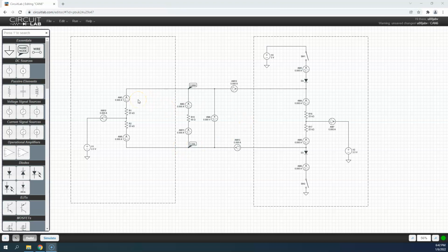So going back to the arbitration and the importance of arbitration, and the fact that we can have one controller trying to drive the CAN bus into a dominant state while the other is permitting it to go to the recessive state. So this concept of you have to drive to the dominant state and you let the system go back to its natural state for the recessive state. So I'm going to try to explain that and show that a little better.